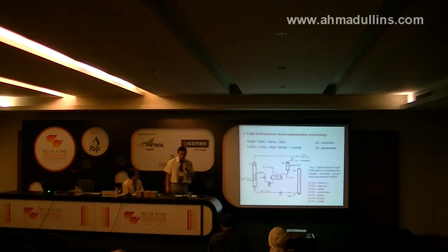In Sweden, propane and butane fraction was cleaned of mercaptan up to 5 ppm weight, but the total sulfur content found by international standard was about 50 ppm weight. And to reduce total sulfur content up to 35 ppm weight, this fraction was subjected to advanced adsorption purification using zeolite.